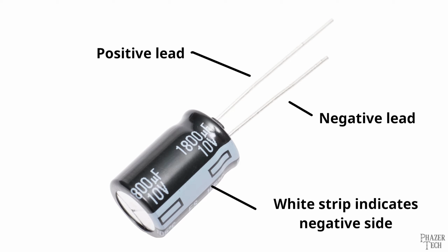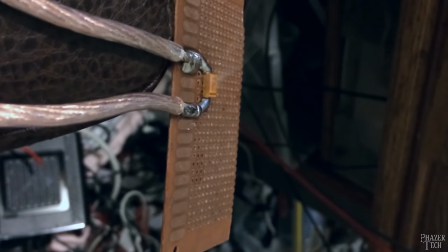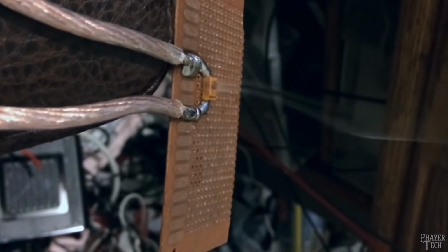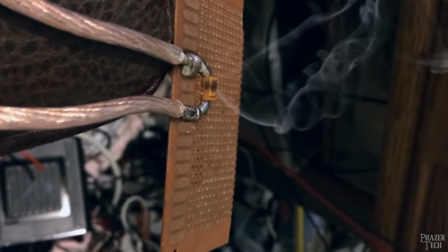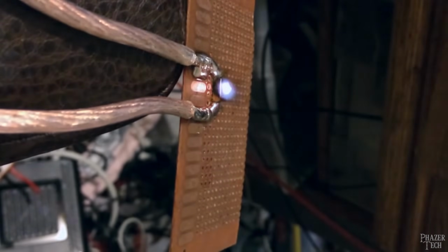Electrolytics cover large capacitance values of at least 1 microfarad and can reach more than several thousand microfarads. These are typically found in power filtering applications. Tantalum caps are also polarized and are more compact than electrolytics. But tantalum caps aren't as common these days, mainly because they're a lot more expensive and they fail in a spectacular fashion. If there's a failure on the board that causes the current to flow in the opposite direction, or if tantalum caps are connected the wrong way, they will typically catch on fire and might even explode, so it's important to ensure you connect polarized caps correctly.